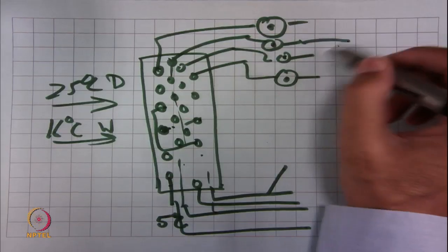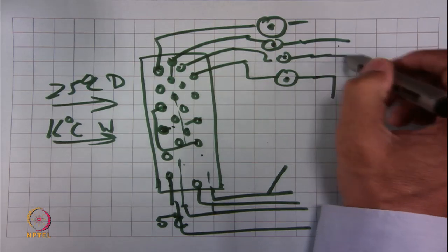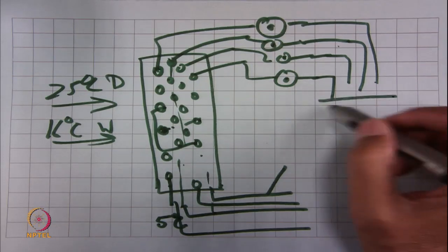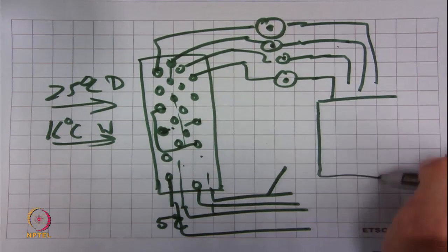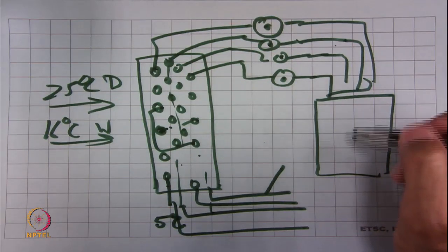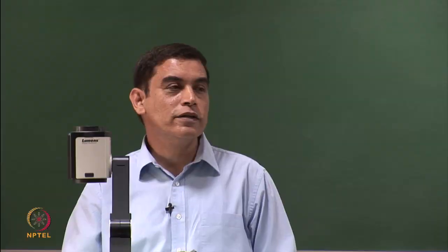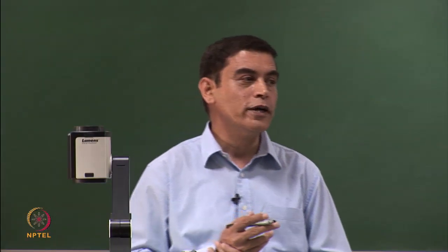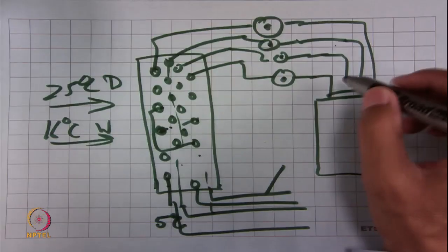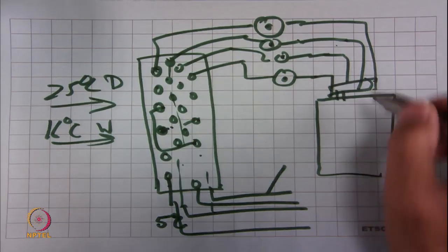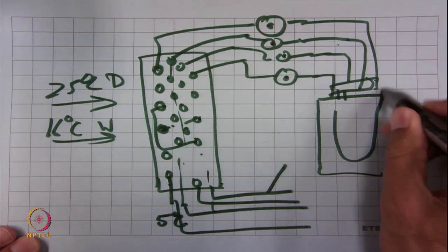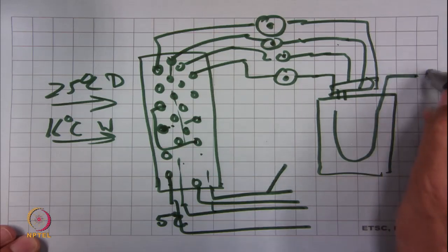The next risk in a system is of low load leading to some refrigerant in liquid form getting to the compressor. So, what we did was we put in an accumulator, and I have not discussed an accumulator with any of you before, right. It is just a device which will take care of all liquid getting entrapped and only vapor going to the compressor. So, this circuit actually gets into a header, and the header is feeding the accumulator, and inside the accumulator there is a tube which goes to the compressor suction.